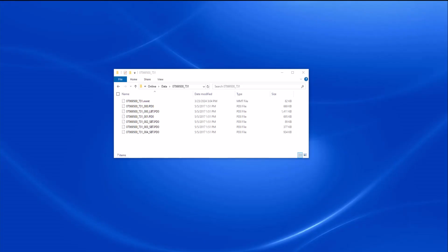To begin, let's look at an actual TRDI measurement. In the previous session, I indicated that you only need to open the MMT file in QRevInt. While this is true, the MMT file is only part of the entire measurement. The MMT file is an XML formatted file that contains user-provided information, the system test, compass calibration, and evaluation, and the file names and paths to the actual raw data.